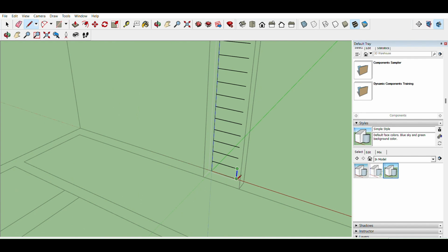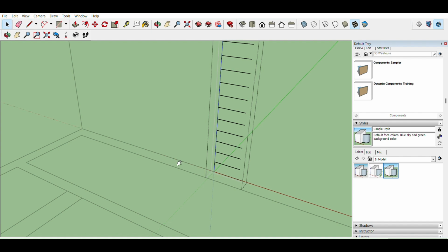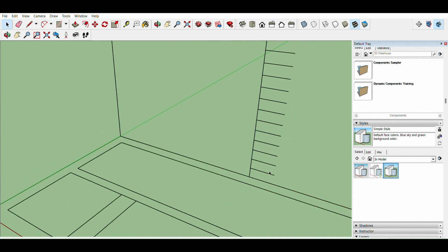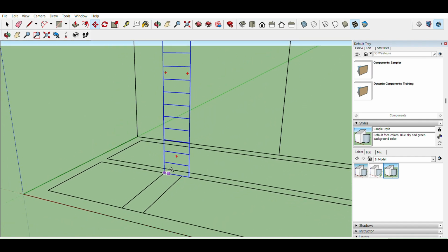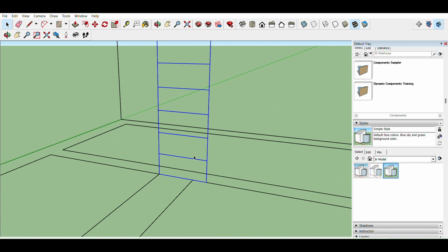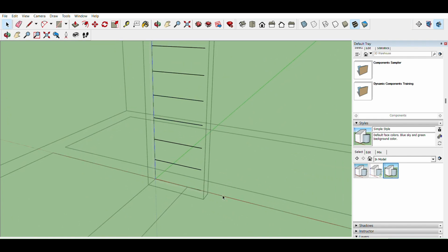That's good. It wants to be under 7 inches, or 7 1/4 or something like that. You kind of get fine-tuned in there, but 6 5/8 is a good public stair with the 11-inch run. So now I know the geometry of this. So let's start doing some steps.